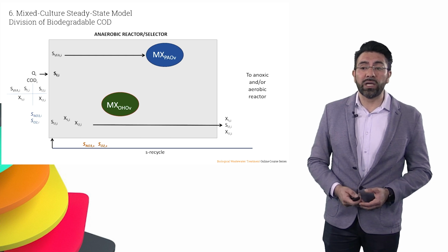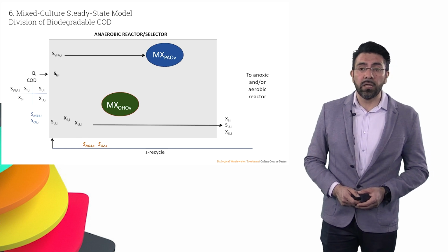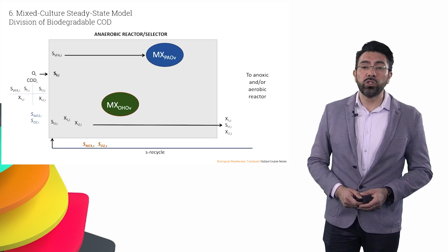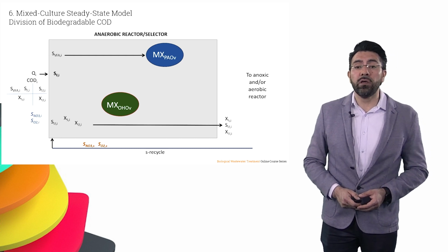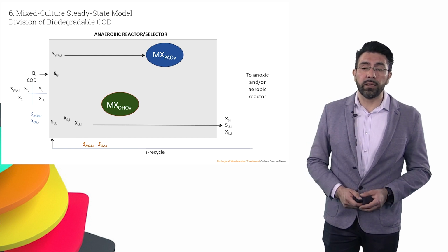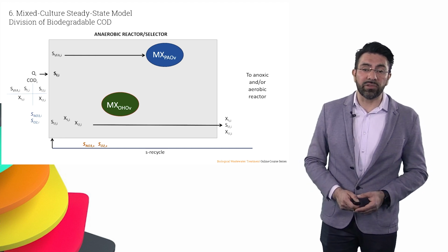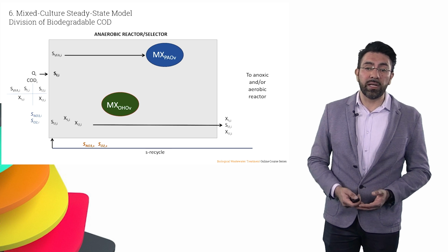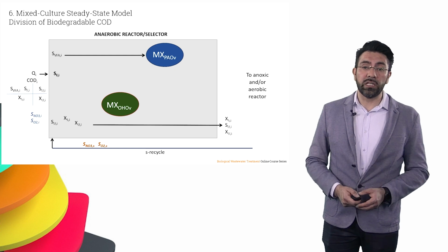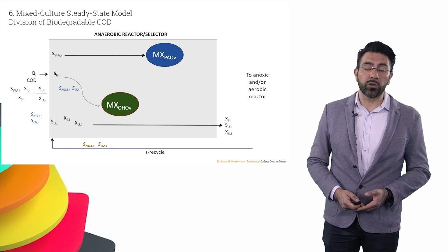We have anoxic reactors, we have aerobic reactors, followed by final settlers or secondary settling tanks, and all of them are exposed to different hydrodynamic conditions that may lead to the intrusion of oxygen, or, if the denitrification step is not working at the highest efficiency possible, or naturally, if it is working but there are some traces of nitrate, we run the risk that nitrate is present in the sludge recycle and also oxygen could be present. So the model considers this potential intrusion of these two electron acceptors, nitrate and oxygen.